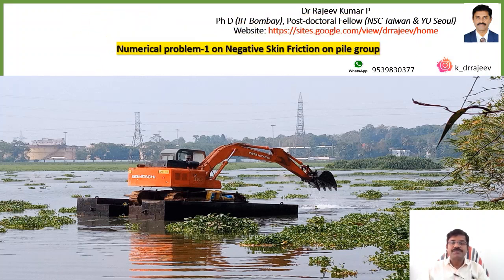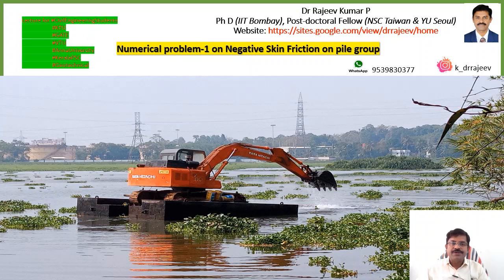Today I am going to discuss with you a numerical problem on negative skin friction on pile group. Negative skin friction, or downward drag, is a phenomenon that occurs when a soil layer surrounding a portion of the pile shaft settles more than the pile. This downward drag on the pile surface, when the soil moves down relative to the pile, adds to the structural loads. This negative skin friction has an effect on reducing the allowable load on the pile.